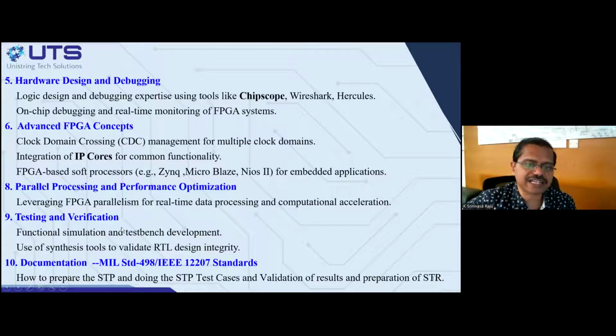In writing the test bench, we do a lot of scripting, which has commonality with ASIC verification, but is mostly applicable to ASIC signal processing chip verification, not the popular AXI-based ASIC verification. We will not be talking much about that. We'll still be doing AXI-based design, but mostly connected with the FPGA. This verification is more about writing test benches, integrating with MATLAB or a C program, or scripts related to Perl or something like that, where you can automate the FPGA-based verification.